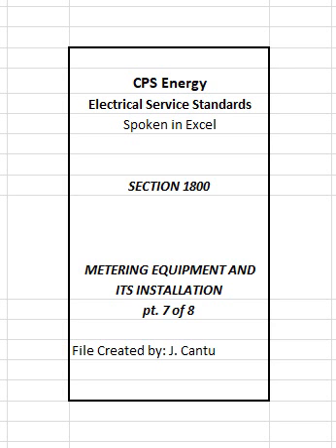4. Address markings must not be obscured when meter sockets, meter enclosures, and disconnecting devices are painted. Address markings and other identification markings must remain legible. Glass meter covers on meters and glass windows in meter enclosures shall not be painted. 5. Meters must be wired, and related switches addressed in the sequence shown in figures 1814 through 1817. CPS Energy must approve exceptions.